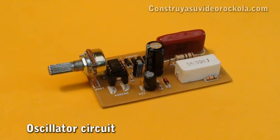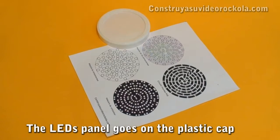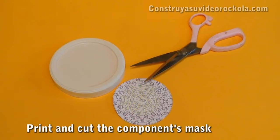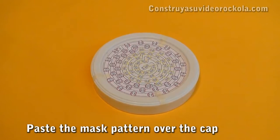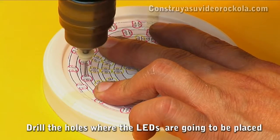Having built the oscillator circuit, we must make the panel of 80 LEDs. We will use the lid of an ice cream jar. The mask is printed from the components found in the PDF file and then cut with scissors. Paste the mask pattern on the lid and, with the help of a drill, drill all the holes where the LEDs will go later.